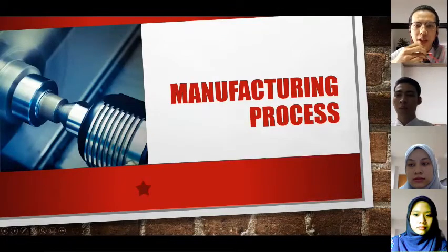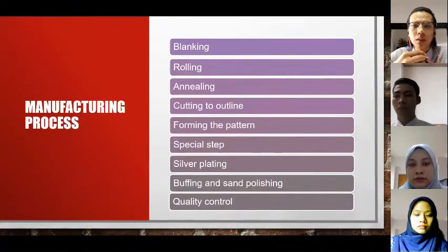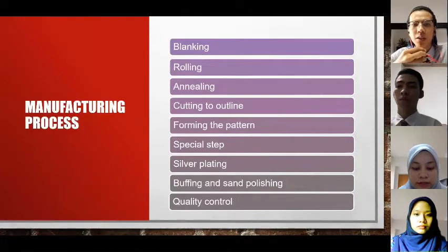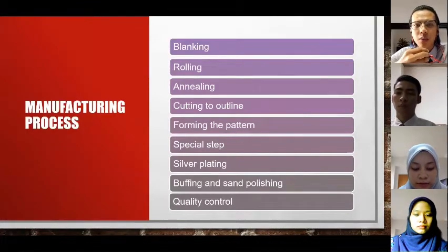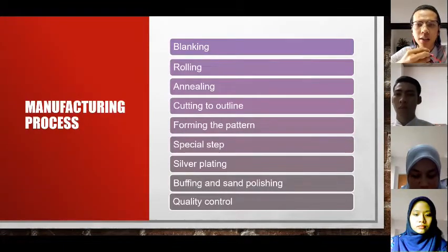Okay, my name is Hanif Muhammad Akbar. Next, I will discuss the manufacturing process for cutlery. The manufacturing process has nine steps. First, blanking, rolling, annealing, cutting to outline, forming the pattern, special step, silver plating, buffing and sand polishing, and lastly, quality control.